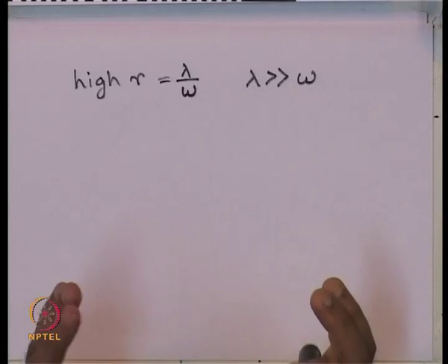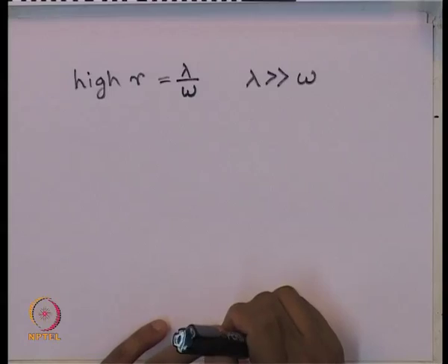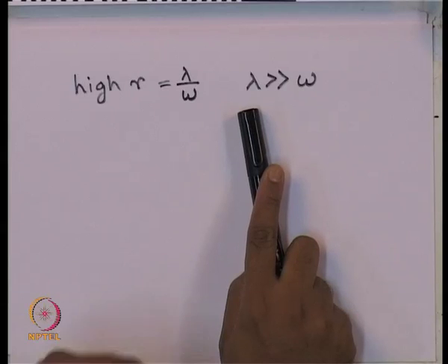As a civil engineering designer, when we are going to design a machine foundation, we hardly have any control on this lambda, because it is given by the machine producer or the manufacturer of the machine. So, they give us the input parameter, that is, at which frequency the machine will operate. It is just an input parameter for us civil engineers or machine foundation designers. What we can control is the natural frequency of the system.